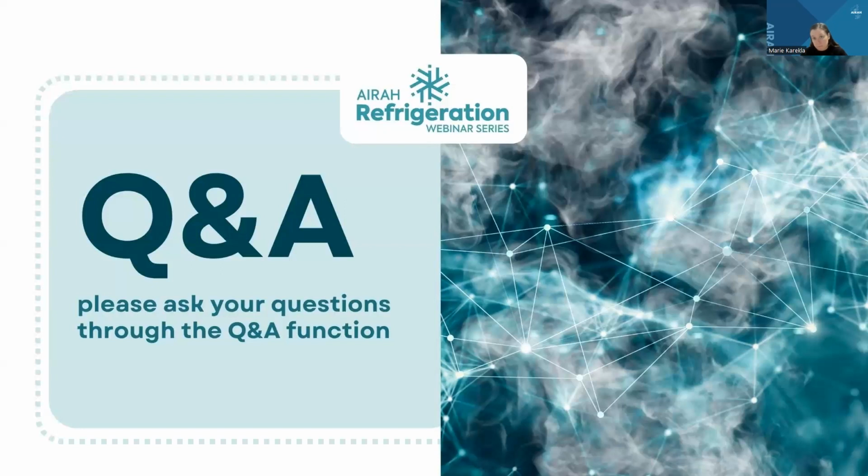Using fresh air in the freezer, again, I'm not aware of. Jonathan, can you answer that question? You come across ventilating freezer rooms for people working in the room as a requirement under 1668, Part 1. Generally, there aren't a lot of times when the freezer room is classified as an occupied space.